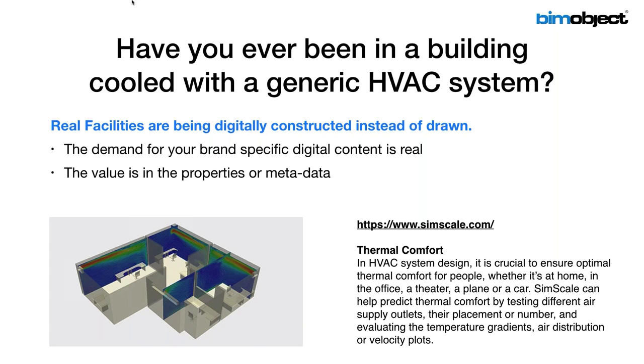We see often that their products are being specified, but we really don't want to use them because they might have the digital geometry, but they don't tell us what the various airflow coefficients are through that VAV box, or even what the weight of that unit is, or many other properties, digital constructs that are attached to that particular system."